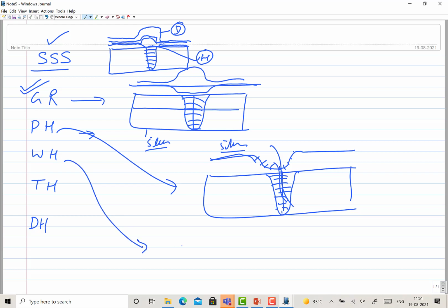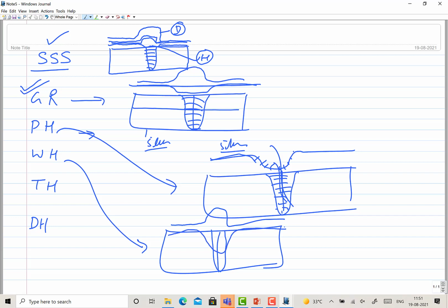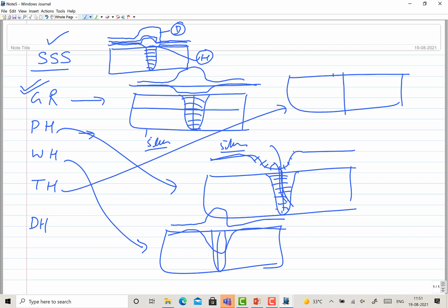On the other hand, if you talk of work hardening metals joined primarily by the deformation, not by the heat, then you will notice that the hardness increases at the joint interface. And if the heat is dominating, then certainly you will get the reverse trend in work hardening metals, because the application of heat will cause huge recovery and recrystallization. That will lead to the loss of all the hardness you had gained from the work hardening of the metal. Transformation hardening metals invariably show increased hardness and strength.